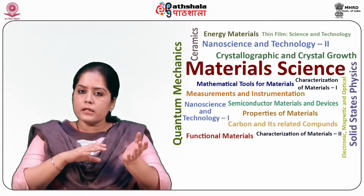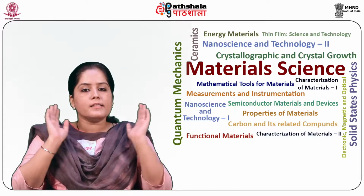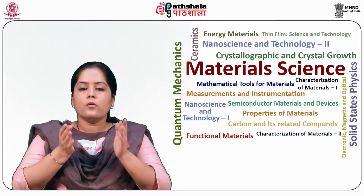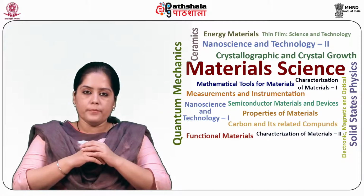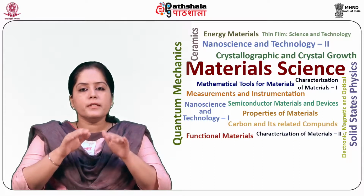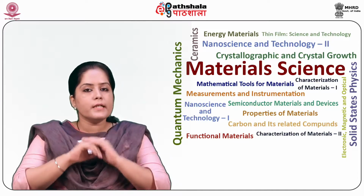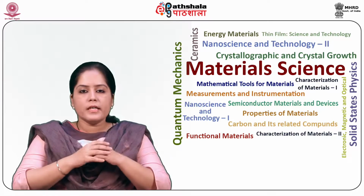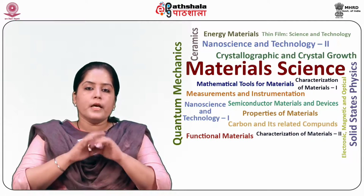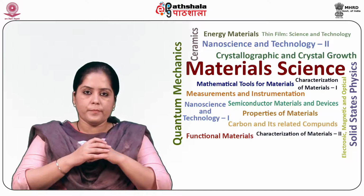Therefore, both inert and reactive gases can be used as the background gases while depositing film. A carousel for holding multiple targets enables the deposition of multi-layer films without the need of breaking the vacuum while changing the material in between.